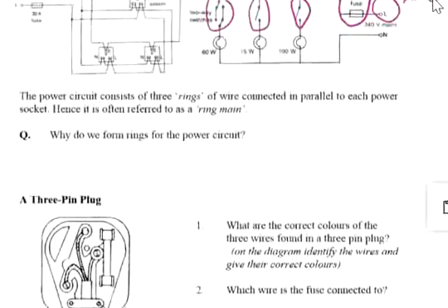Alright, so this one is earth, green and yellow. This one is live, which is brown, and of course this one is neutral, which is blue.